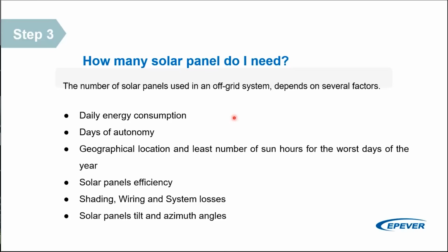You will see numbers like VOC and ISC, and these are the two important characteristics we will be using in designing the standalone system. VOC, or open circuit voltage, occurs when the positive and negative leads from the solar array are not connected, and this results in the highest voltage the cell can produce.